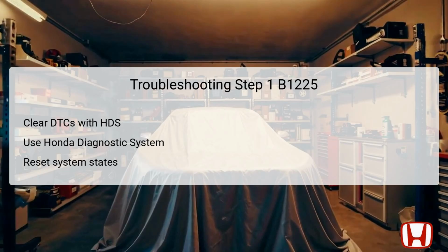Resetting the system states can help eliminate false readings that may have occurred due to previous malfunctions. Ensure that the vehicle is in a safe state and the ignition is turned on as you utilize the HDS to clear the codes. After completing this step, it is essential to proceed with the next debugging steps to thoroughly evaluate the temperature sensor circuit.